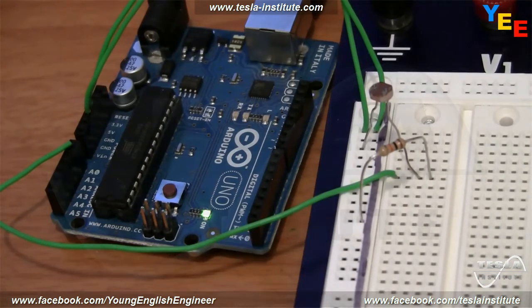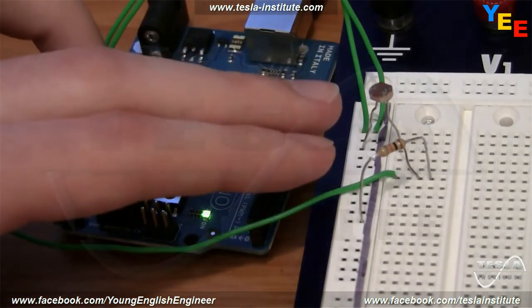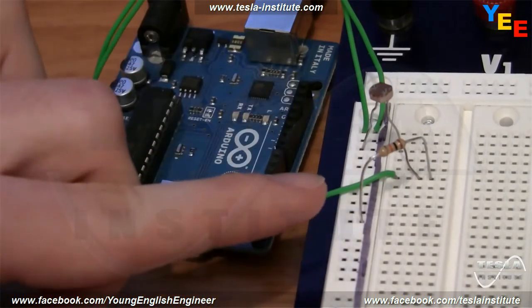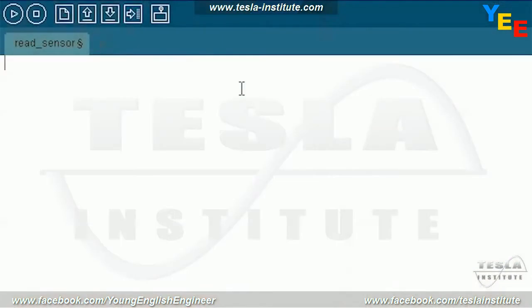Now let's program this to show us the values from the photoresistor as we change the light in the room. Note that you can change the position of the photoresistor and the fixed resistor, and the values in the computer will inverse. Let's write a quick program that will show us the value of this sensor. So first we'll need to define our input pins. We'll call it sense pin. That's going to be equal to analog input on pin 0. Now we always want to do our setup function.